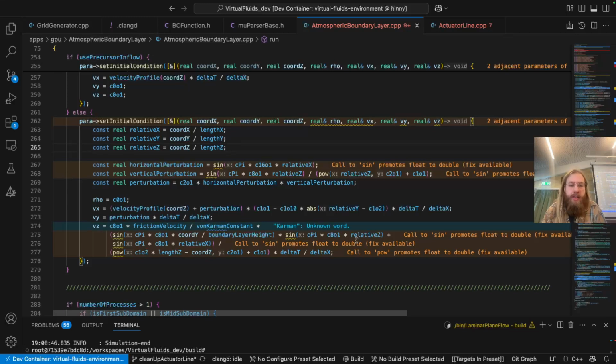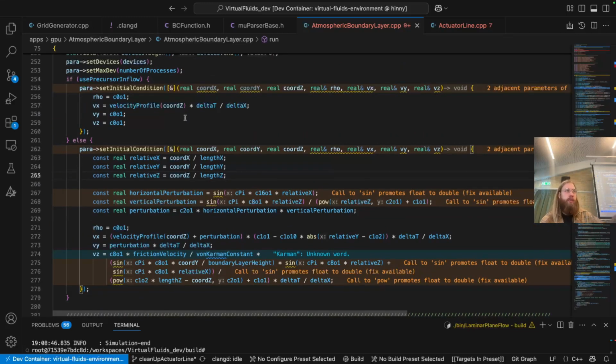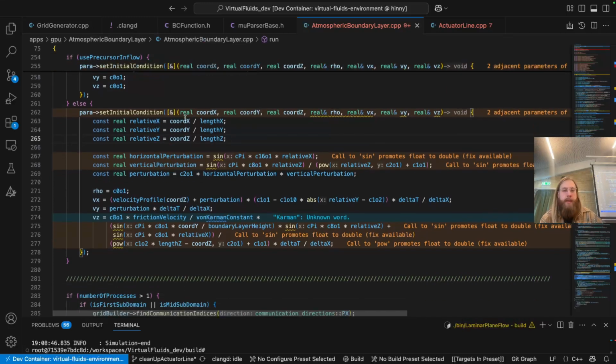this very specific way of initializing it kind of triggers the generation of turbulence the fastest. We didn't come up with this, someone else came up with this, but this is what we find. So if you just initialize your domain with the log law, it's going to take a very, very long time. You're going to need a lot of spin-up time. And of course, LBM is fast, but you're still producing a lot of heat that you don't need to. So we find that this triggers it much quicker. Is this divergence free? This is divergence free, yes.